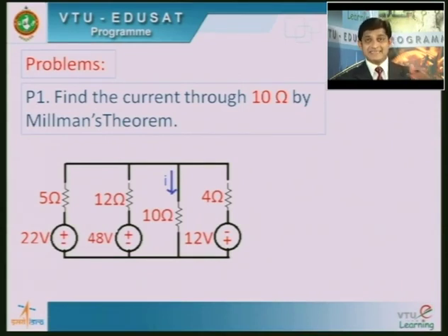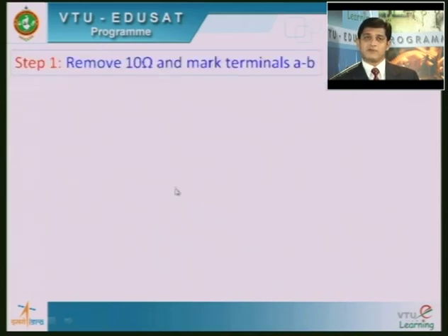We used to disconnect the branch through which the current or the voltage was present. Okay. So, after disconnecting, what happens? We avail the two terminals, the open circuit terminals. So, across those two open circuit terminals, we need to obtain what is the equivalent circuit or the network. So, that is what we shall try doing here also. So, in the solution, the very first step deals with disconnecting this. Fine. So, that is what we will be doing.